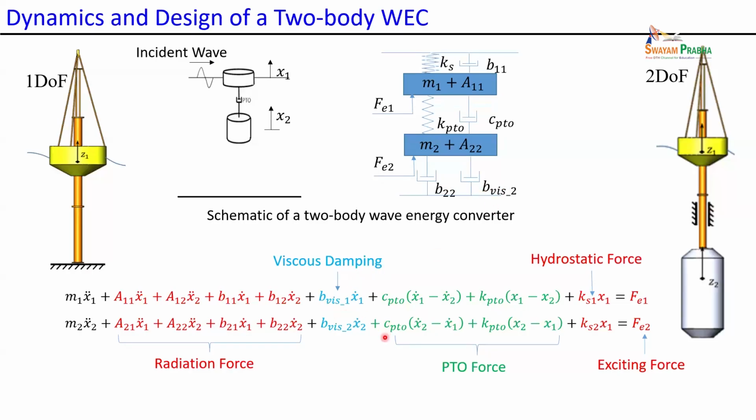Okay. Now you are also going to have PTO damping, PTO stiffness. Sure, you will have PTO inertia. I didn't write it here. You can add another inertial force in between, M PTO times the relative acceleration. Okay, so here you have hydrostatic stiffness. First stiffness, this is proportional to the cross-section area here. Second stiffness, proportional to this smaller cross-section area, right?